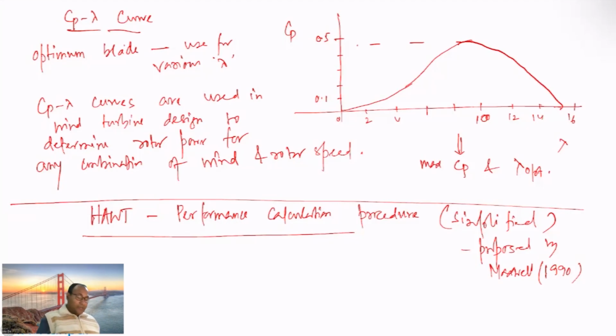Obviously, this method also uses the blade element theory that we have talked about, and also incorporates those analytical methods for finding the angle of attack, CL, and induction factors. Now, depending on whether tip loss is included, few or no iterations are required. If you include tip loss, definitely it goes into some iterative procedure. If you do not include the tip loss, then this doesn't include anything. So obviously there are two conditions under which it applies.